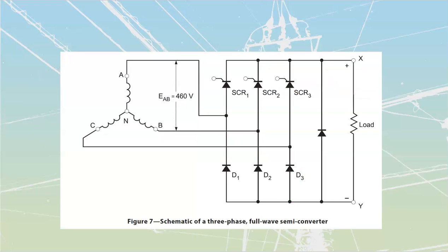Moving on down through here, they give us 3-phase full wave semiconverters, and then we have 3-phase full wave converters as well. Semiconverters are less commonly used. You might find them in old installations. They are still kicking around and haven't died, because a lot of our semiconductor components will last a fairly long time if we don't have spikes, if we have good quality voltage on there.